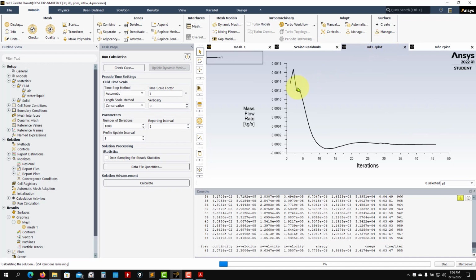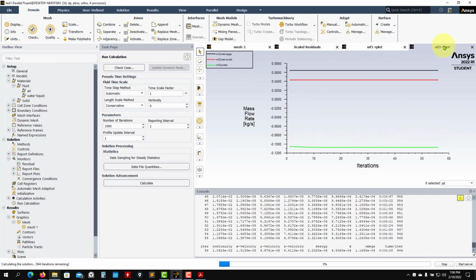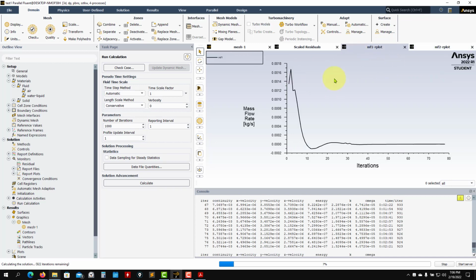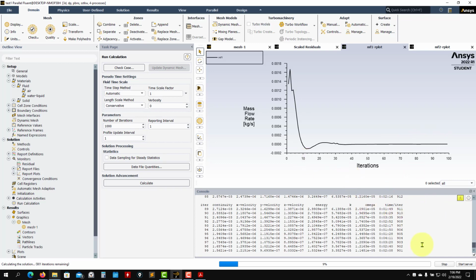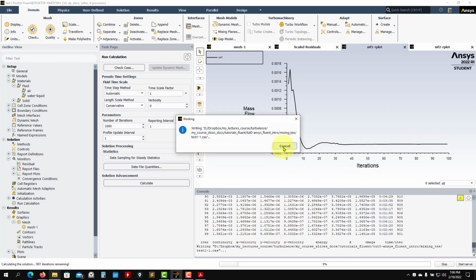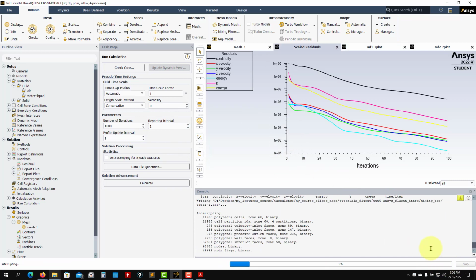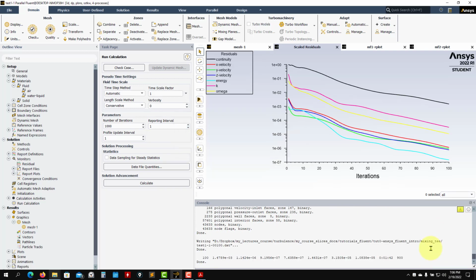See that this is the mass flow, the summation, and mass flow by individual boundary surfaces. And see that it is conservative, about 0. You can stop the simulation. As you press here, you see that you have the stop here. As you press stop, it will stop the simulation, and then you can keep iterating, okay? So let me show you.